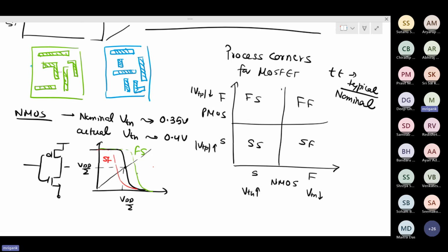Whatever masks, oxidation process, and doping processes are used for NMOS fabrication, all the MOSFETs will be fabricated in the same step. Likewise, for the PMOS: N-well creation, gate oxidation of that N-well to get the oxide, and then the doping of the source drain region, all those things will be done using the same steps. So all the PMOSs sitting in different N-wells will be fabricated in the same steps, right?